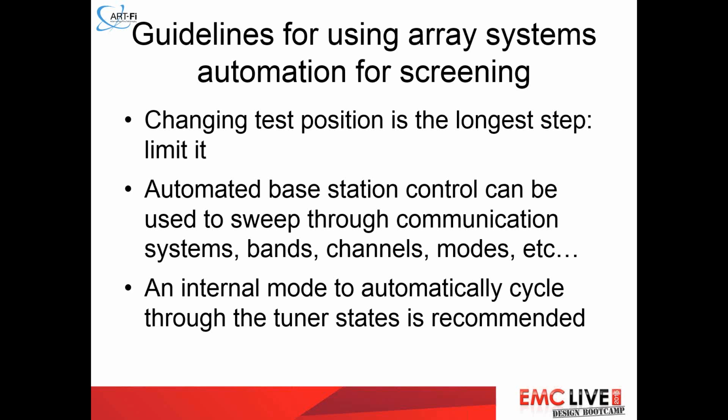Also, for devices using an antenna tuner, it may be very interesting to have an internal software mode, or an embedded software mode, that allows automatically cycling through the tuner states and can eventually be synchronized to the fast SAR system. That can definitely be pretty useful, but only the mobile manufacturer can do that.